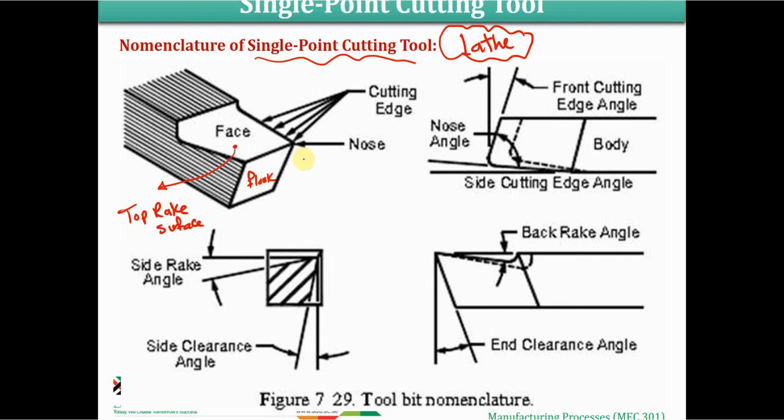And there is another flank surface which is not seen from here. This is another flank surface of the tool itself. And this is the nose, which is the nose radius, or this nose, which is just a little bit curved, and it is not just a point. It has a very small curvature to initiate the cutting, the same concept as the chisel edge in the twisted drill. In the meanwhile, it should be very small to allow for the penetration of the tool inside the workpiece. And this is going to be the main cutting edge that we already talked about here, right?